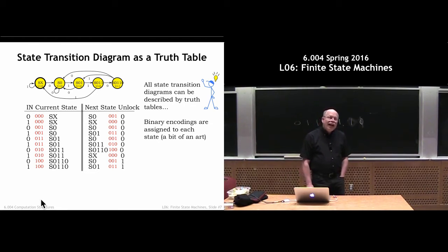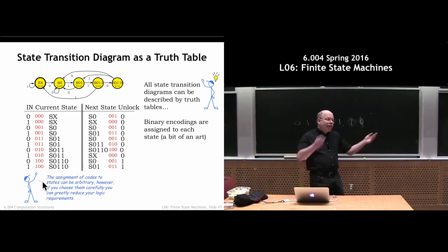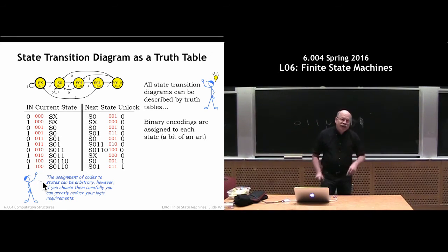The choice of the actual binary encoding to use for every state influences how complicated the logic is that you need to design. If you're using a ROM, it's pretty arbitrary, but if you're using real combinational logic, you can sometimes simplify the logic a lot because of the way the Karnaugh map works out, by choosing a clever encoding so that it minimizes the logic that you need.